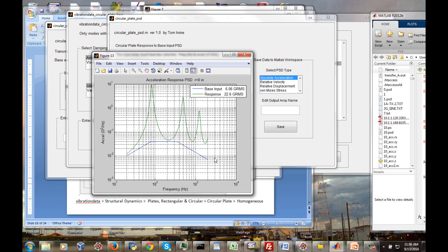So say, for example, we have a bulkhead and we have a small avionics box. We'd want to make sure that the natural frequency of the circuit board inside that box did not coincide with any of these plate modes. And we also might want to think about, well, could we add some damping treatment to that plate or do something else to increase the damping, because we're getting some quite high responses there. And again, each of these modes is a Q equal to 10 mode, and you could verify that doing the half power bandwidth method.